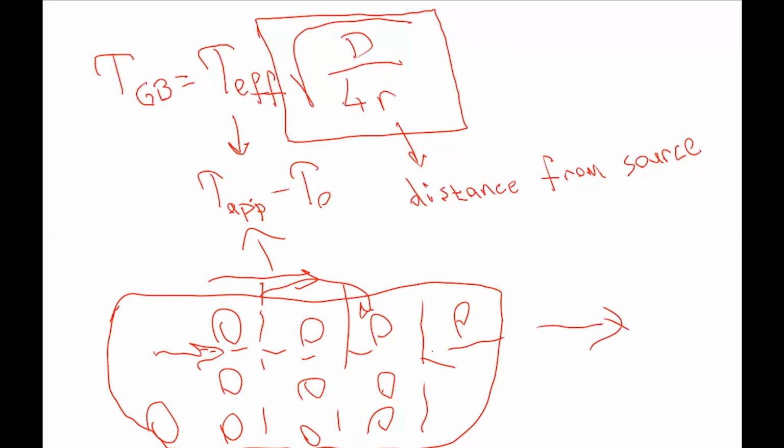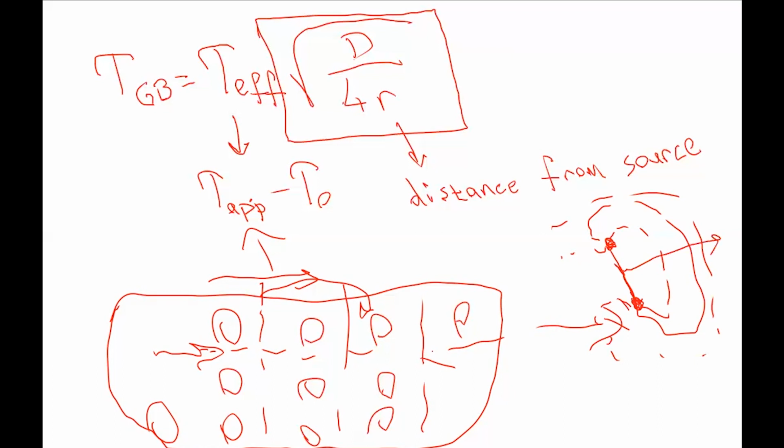So the Frank-Read source is the original source of the dislocation, and we generally represent them by discrete lines. It will elongate, elongate, elongate. Then it will lead for its movement. And we need some shear stress to activate dislocation movement.